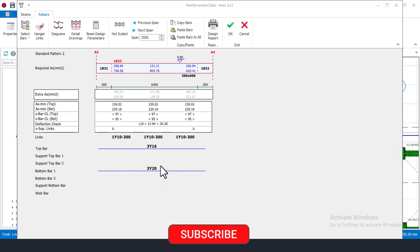So when you're doing your beam interactive design, it's good to try to use smaller bars first, and only if they are not sufficient do you go to a bigger bar. Like I said before, while you keep the stability of the structure in mind, also keep the cost of the structure in mind. It's very, very important. A good design must be stable and also should not be too costly. So also put the cost in your mind.